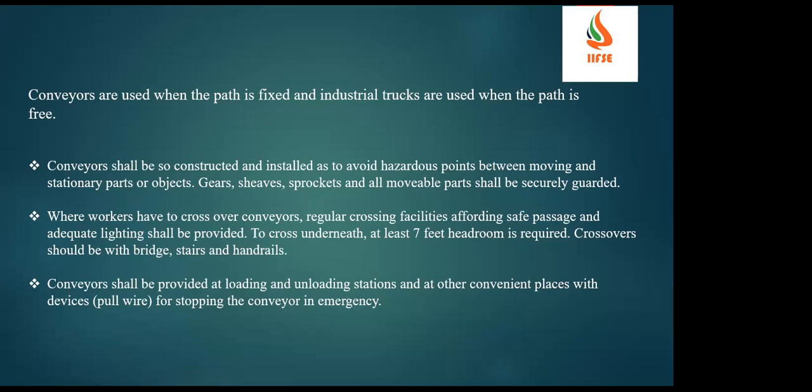If you are using a larger one, and the part is very small, you should not apply the belt properly, it will slip out from that. Because if you are increasing the capacity, automatically the belt width will increase. Because of that, we are not able to apply it properly. So if you are lifting 1 ton, you can go for a 2 ton belt. That is more than sufficient.